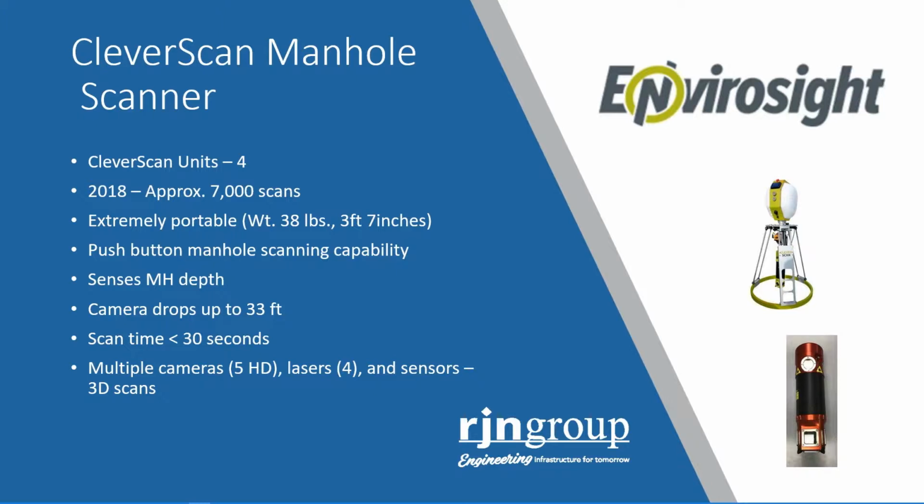IBAC and other systems may be a bit of a challenge to take into more remote places. The limitation on the CleverScan is the distance for the depth of the manhole. The cord length is about 33 feet, and I would say safely to scan a manhole, anything above 30 feet might be a bit difficult. But in general, most of the manhole structures are within that depth.